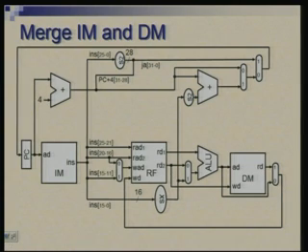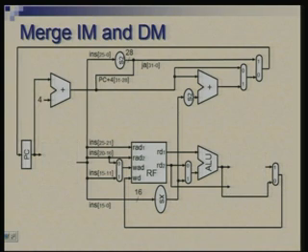So, firstly let us merge instruction memory and the data memory. Replace both these by a single memory. So, we remove these and replace them with a single block which is doing read as well as write, and I have placed it here where program memory was kept, but what we will do is we will route its inputs and outputs back to the same memory.